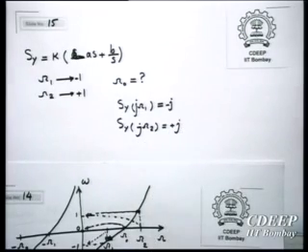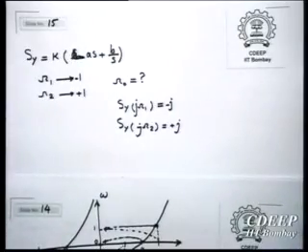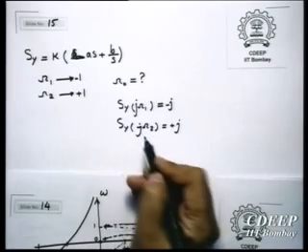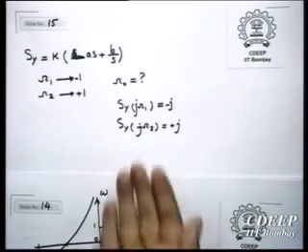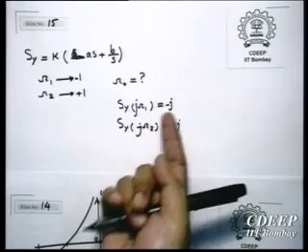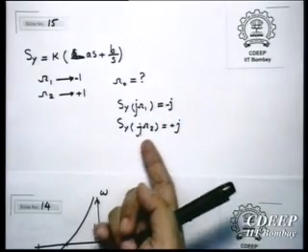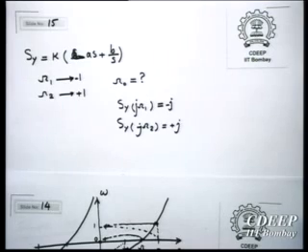So from these 2 relations you can get A and B, and as you notice, this is an odd function, which is also an odd function. Odd means that if you convert omega 1 to minus omega 1 you will get j, and omega 2 to minus omega 2 you will get minus j. So in this way it's very easy. Now we can convert the low pass to band pass. Similarly, converting low pass to band reject, and these are in fact the most commonly used.